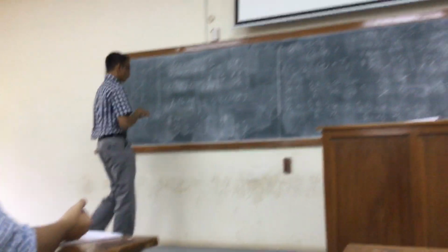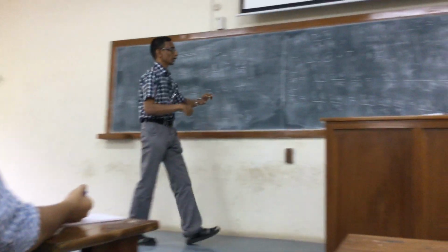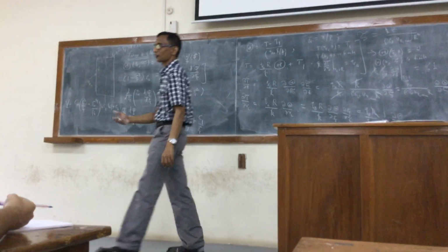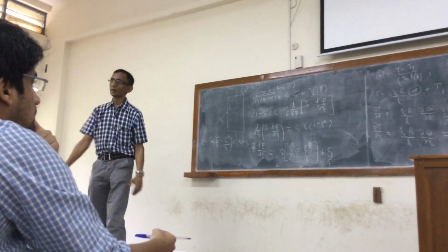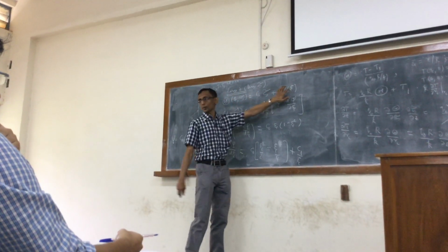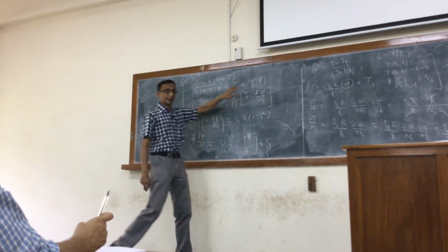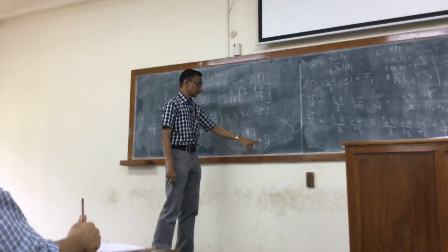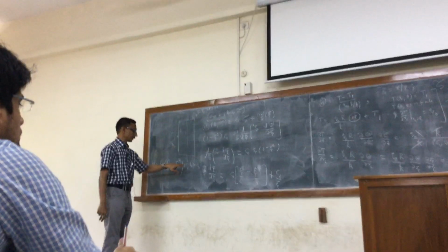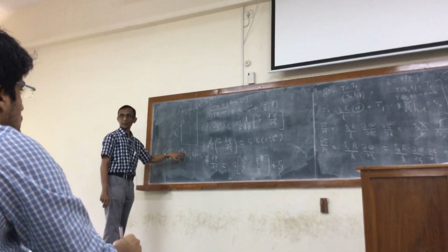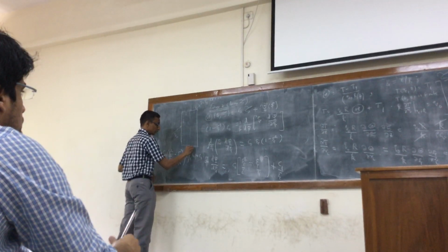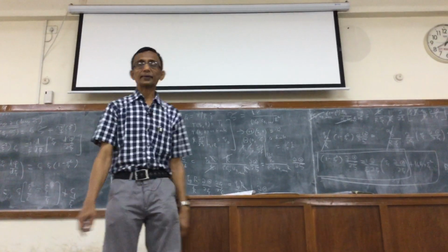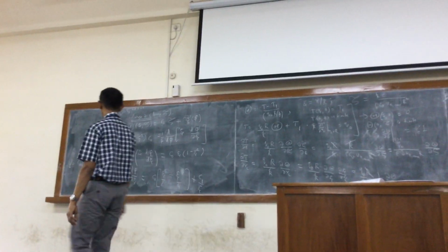Right? So now we have got, so the first condition I will apply is the fact that T at 0 z is finite, which means T is finite, then theta also has to be finite, and psi also has to be finite. At psi, the lowercase psi equal to 0, so clearly this has to be at psi equal to 0. If this has to be finite, then clearly C1 cannot be anything other than 0. Right? So that is the first condition. So C1 equal to 0, I found one condition.